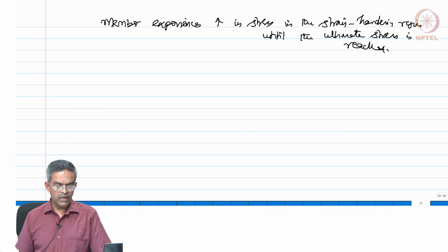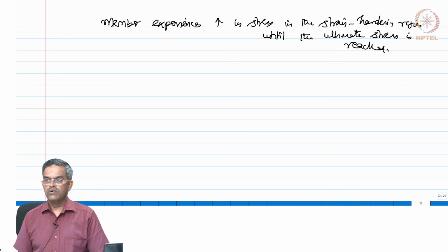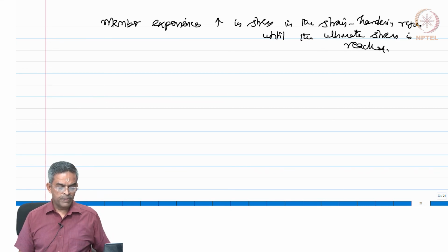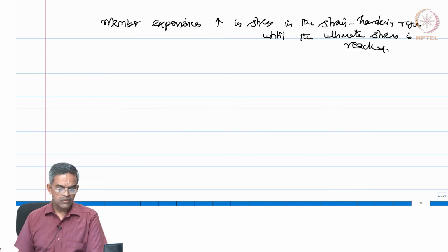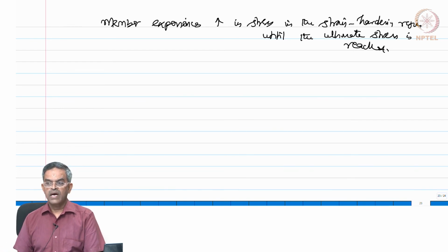So, there will be a difficulty in modeling this scenario in single degree of freedom system. To predict the dynamic response, it would be necessary to continuously vary the material stress with deformation. This variation is difficult to model in single degree of freedom systems, because this requires a complex resistance deflection curve at each point of time to be updated.